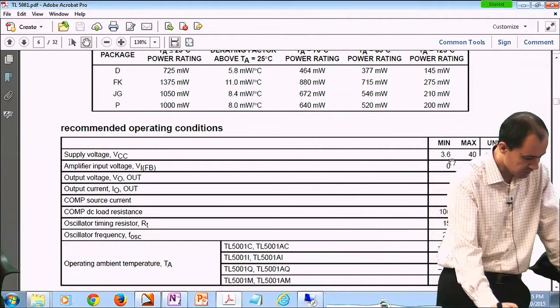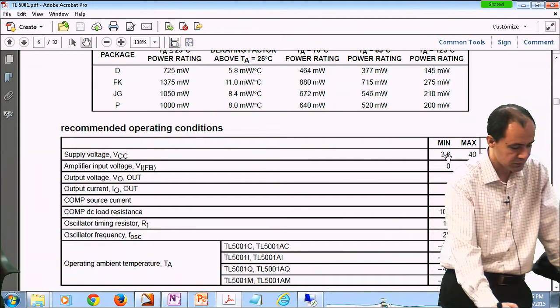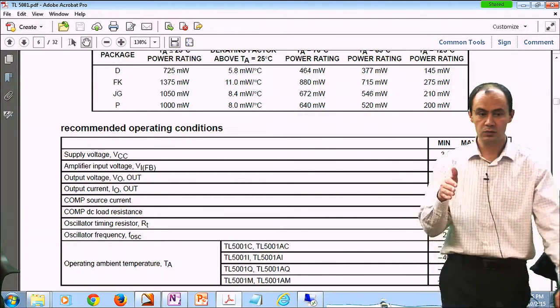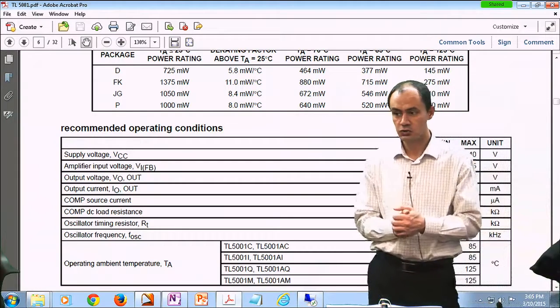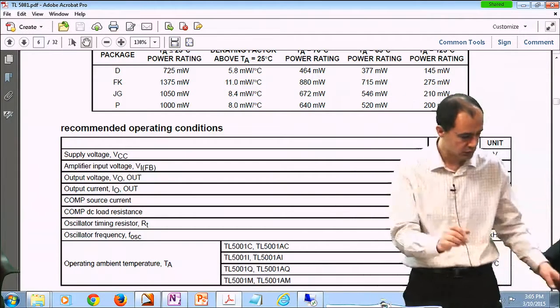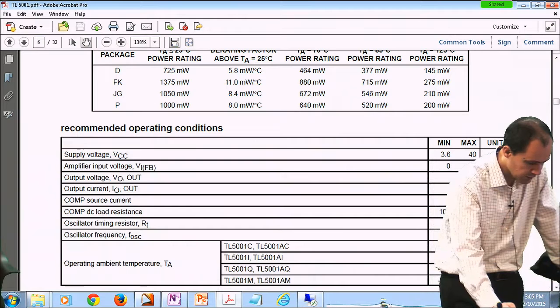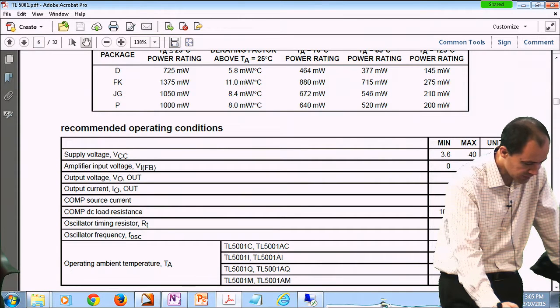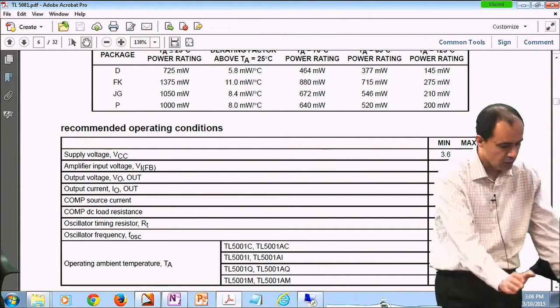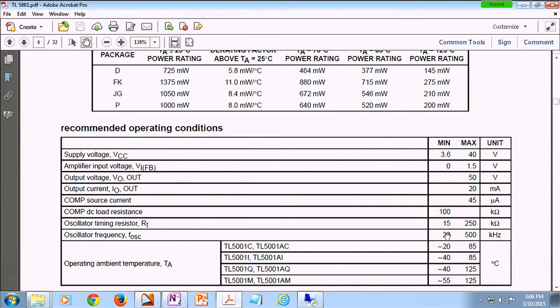So that's very, very good. But that under voltage lockout is if your voltage is below 3.6, in order to command the chip, don't do anything because the input voltage is too small. They have a block over there to turn the whole chip down. Some of these chips, when you're selecting them, actually tell you in what range that oscillator functions. Like here, your oscillator functions from 20 kilohertz all the way to 500 kilohertz. That's actually quite good. Usually, you're looking at 100 kilohertz, 150, or 75, so it can actually easily cover that.